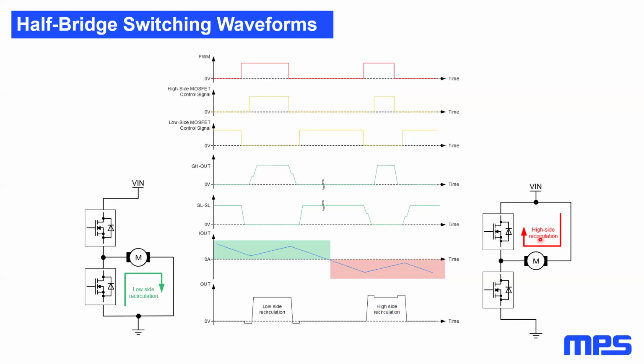In a half-bridge, you should never close both high side and low side MOSFET at the same time. If you did that, you would have created a really low resistance path between power and ground, effectively shorting out the power supply. This condition is called shoot-through and is an almost guaranteed way to quickly destroy your bridge or something else in your circuit.